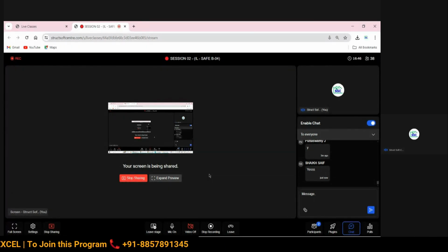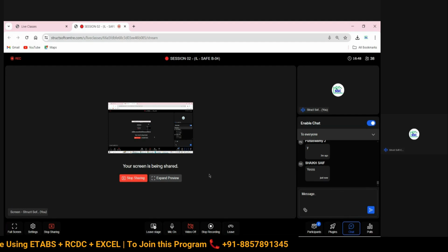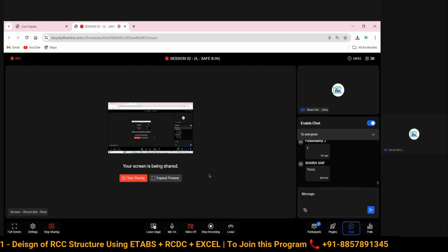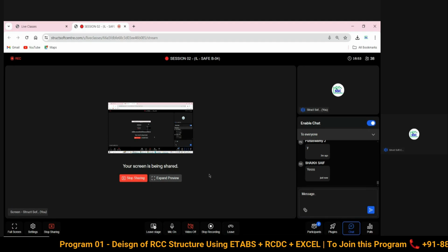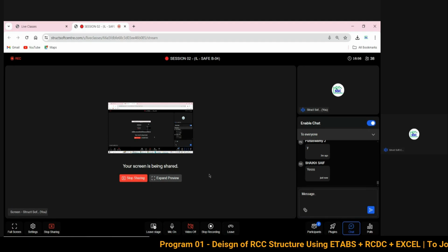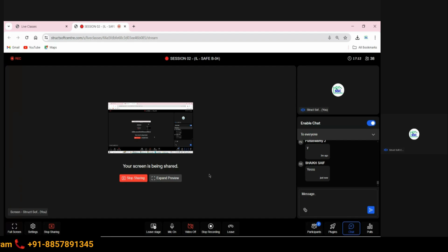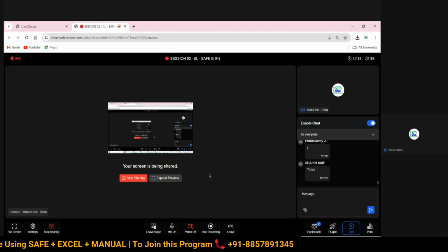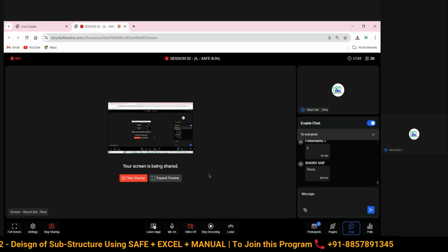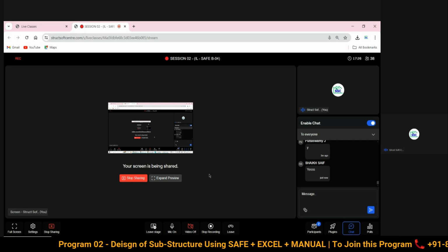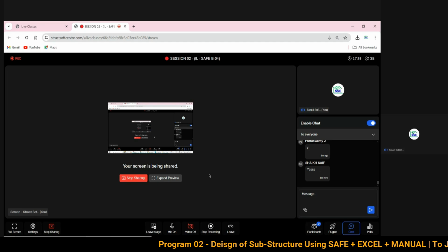But if you are going to deal with a very big project, a very important, iconic project, and there is a demand to do the exploration with more precision at multiple points at a greater depth, it is needed to do the exploration both on site as well as in the laboratory. Both investigations are needed to get the real solution, the right capacity and right properties of the soil. So based on the project and its importance, the method of exploration is adopted